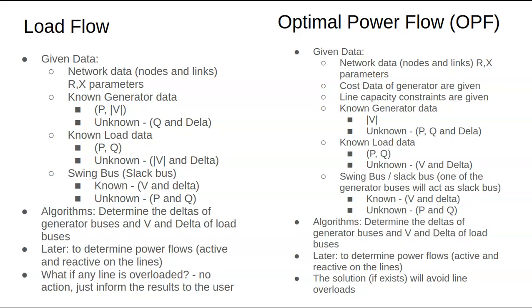Now in the night, your load curve is going only to 80 kilowatts. If it is 80 kilowatts and you have two generators, both 200, 200, you don't have to keep running both of them. You switch one off, so after 11 p.m., switch off this. This problem is called unit commitment. After unit commitment, what happens then? Then the question comes of how much I should generate. Economic dispatch.